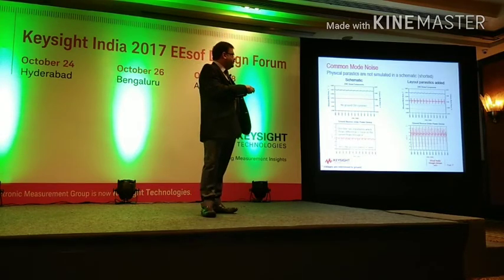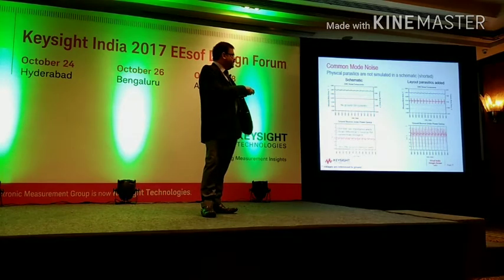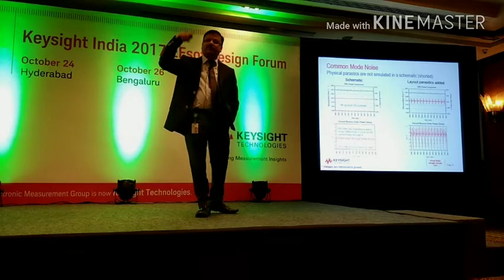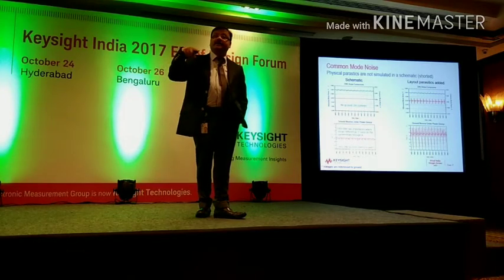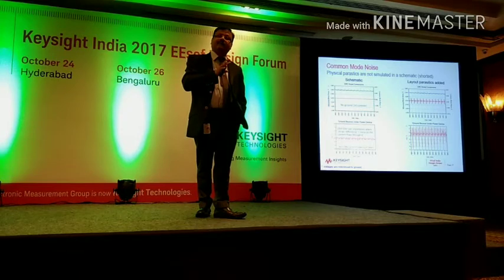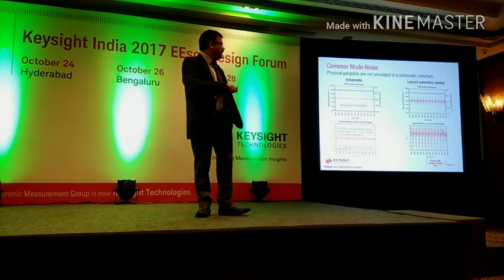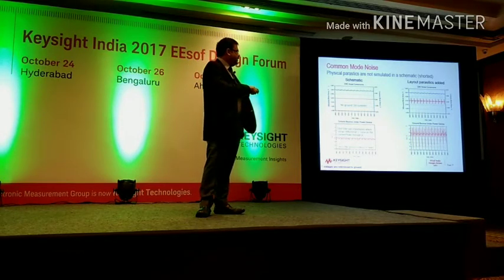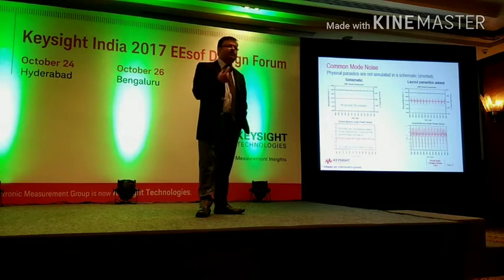Now, these spikes can be as high as 10 volts, by the way. Right? Now, this was with all schematic components. Now we look at the layout, and you suddenly see a higher level of common mode noise. Differential is more or less okay. When you look at the red waveform, the common mode noise is much higher. And that's predicted by the layout, but not from the schematic. I'll tell you the reason why it happens. Yeah. Now, why is layout becoming more important?